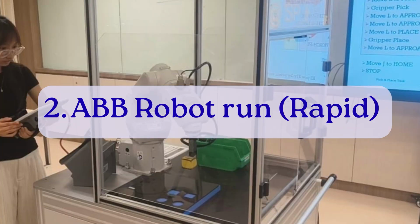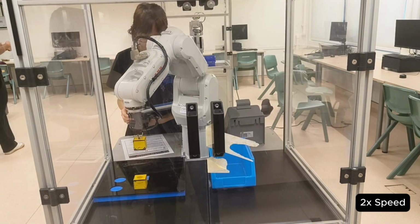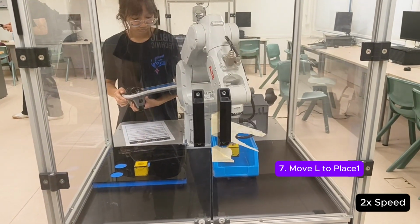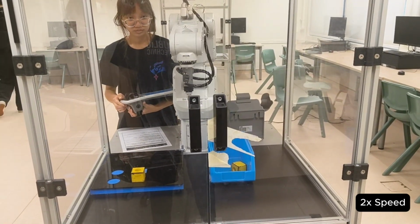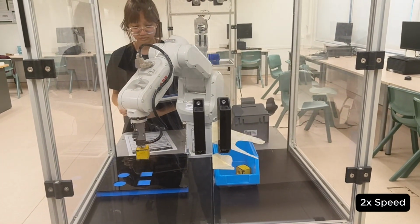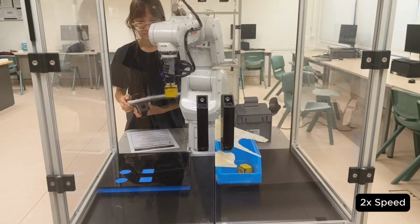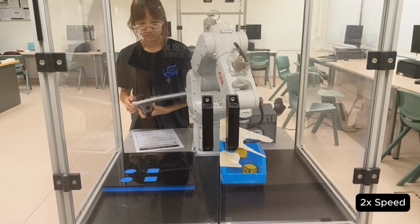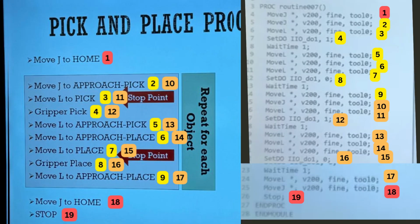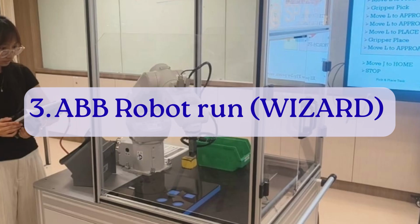Now, I will elaborate more on the ABB Robot Run on Rapid. The same pick-and-place task is demonstrated using the real ABB industrial robot. For this task, the pick-and-place positions were first marked physically on the work surface and taught using the teach pendant. A routine was created to perform the same sequence as the simulation, but in this case, the gripper actively picks up and releases the object into the basket. This is the Rapid code from steps 1 to 19.